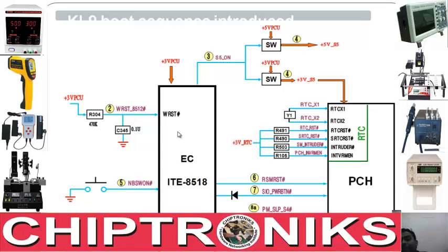As I said in my previous class on digital circuit framework, any integrated circuit requires three things: supply, reset, and clock. Here this +3VPCU is acting as a supply, and +3VPCU here is also acting as a reset, and the clock is embedded. So now this IO controller can work, but not all the parts can work. Only the power management section of this device can work, right? Not all the sections. So the second step is done: reset and supply have already come to the IO controller.